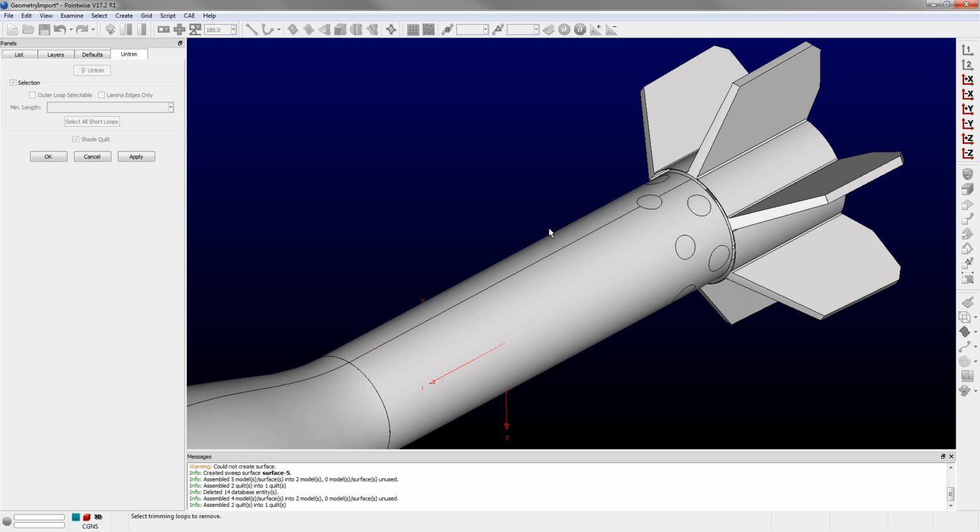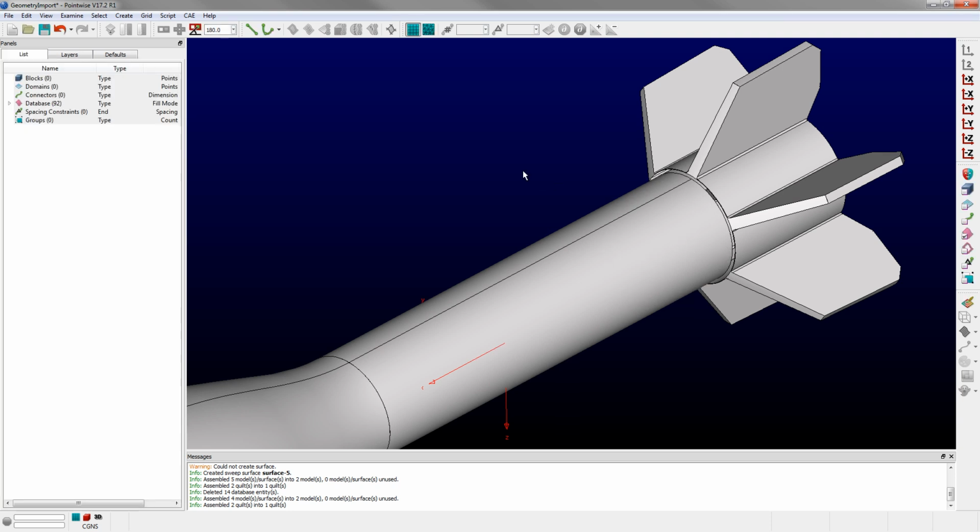So I'm going to do this untrim operation, click OK. I've removed those, and again, if you notice down here, this tells us what we have selected or highlighted. So that's one model. Spacebar again, there's another model. Okay, so I'm just going to delete this one. You'll notice this one doesn't have a seam. It just has two end circles, right? The first model I had has a seam on it. Okay, I want to keep that one, but this one right here, without the seam, I'm going to delete.